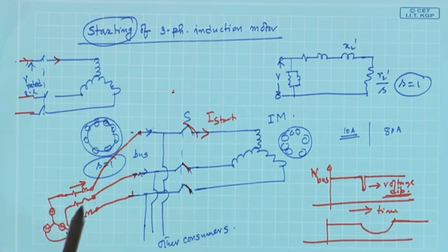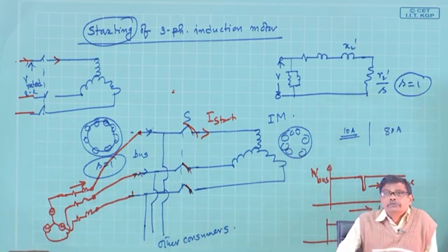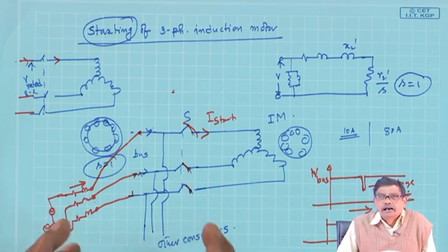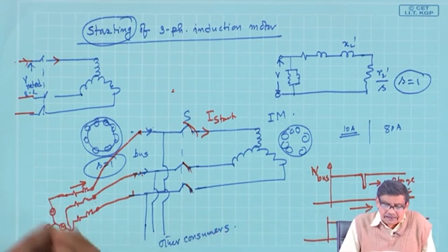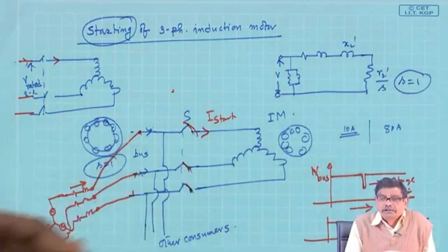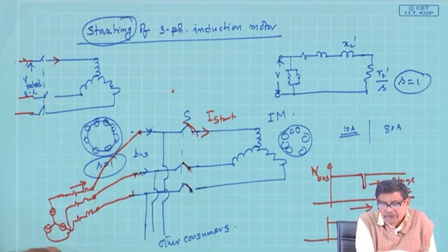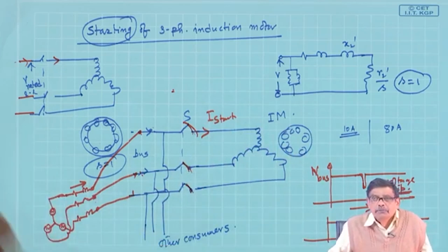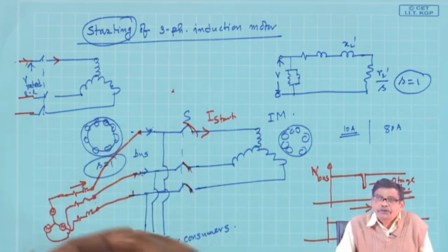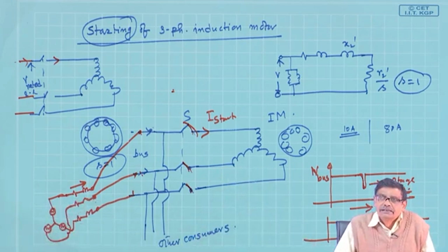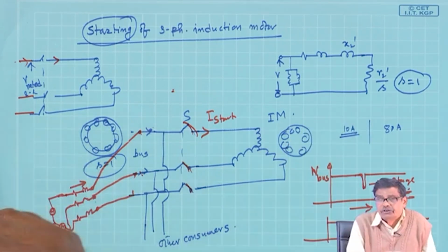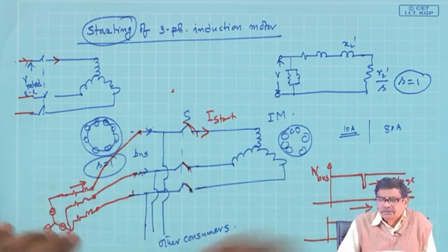No way. There are induction motors used in industry which are to be switched on and switched off at regular intervals of time. Say a rolling mill, you are rolling iron beams. One iron beam comes, you roll it by roller with the help of induction motor, suddenly full load, but the motor is to be started there, and once again you restart with full voltage. You can think that sometimes it is to be started, switched off after doing some operation in quick succession.